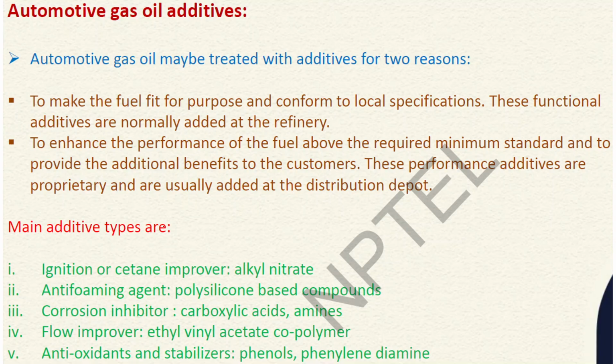Coming on to the automotive gas oil additives. To make fuel fit for purpose and conform to local specifications, some additives are added. Some amount of additives are added to improve its quality, its properties, its combustion quality, as well as to improve the flow and to reduce the corrosion and rusting inside the engine. The main additives are the cetane enhancers, to reduce the delay period of injection to combustion.